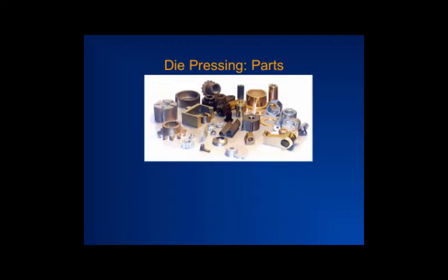So the kind of parts that you might create with something like that have all these kinds of complexities. Okay, so you might see in some cases it's a very simple part like a gear, right? The nature of that die would be such that you would have one punch through the middle and one punch through the bottom, and then you can end up creating shapes like that.